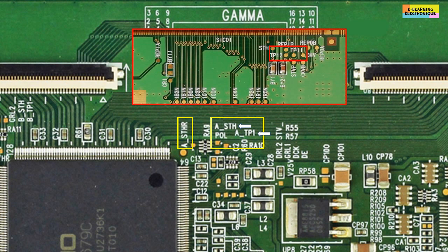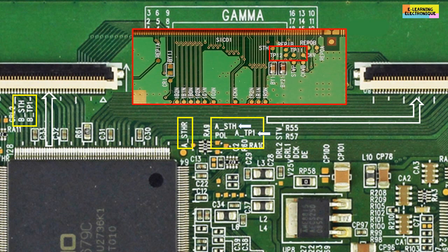In the same way, when there are several source drivers, one can find a number or a letter accompanying the TP inscription of totem pole to locate them compared to each chip of source driver. On this TCON board with 2 connectors on the panel, a letter A or B has been put in front of STH to differentiate them according to their direction on the connectors. Same thing for TP, to which the number 1 has been added.